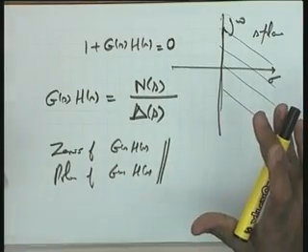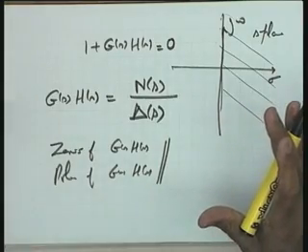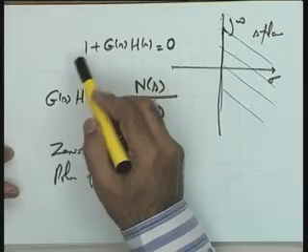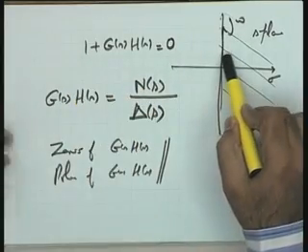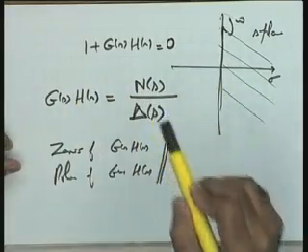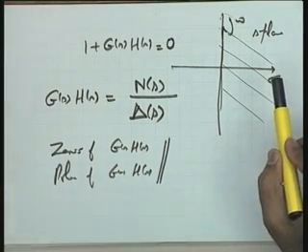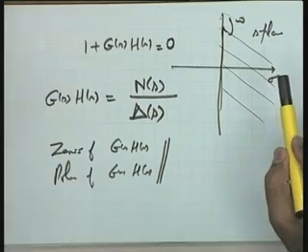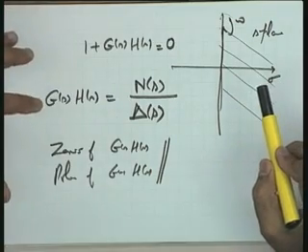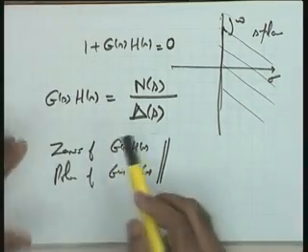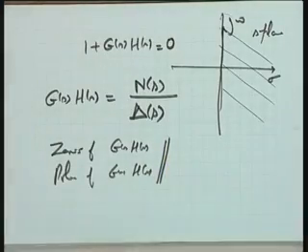But a system may be open loop stable or open loop unstable, it does not matter, because I want to study the stability under closed loop. My question is that the system under closed loop should be a stable system, because a feedback system or feedback principle has the capability of stabilizing an otherwise open loop unstable system. So you see that if you are given an open loop unstable system, it does not matter. It means your plant is open loop unstable and you want to study the stability properties when the loop has been closed, that is under feedback.